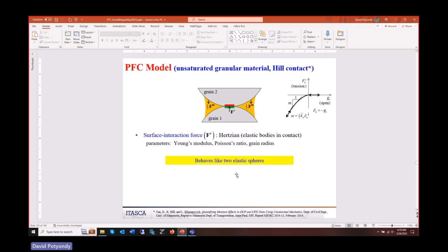Now, he only was able to solve the problem for normal overlap, but in reality there's also shear overlap. There's shear motion, I mean. And so then there was a guy named Mindlin who was a professor in 1953, and he attacked that problem, and he actually solved that problem. I don't have the plot, but if this was shear force, you get a similar, not the same shape exactly, but a stiffening effect also in the shear direction.